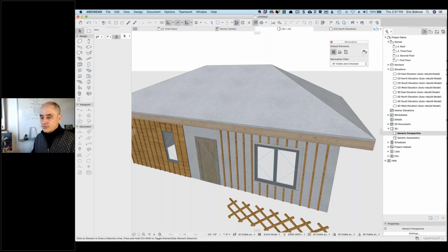All right. So Chris says, I have Snap-on. I'm not sure when that was and if that caused the issue. You can also use an empty opening in the wall or door tool. Yes, so you can use an empty opening rather than the opening tool for that. Okay, so the opening doesn't have to be linked to one wall. Then it cuts more than one wall. I haven't used the opening tool very much, and so that's something that I guess I will play around with so I can get more comfortable with creating those openings.